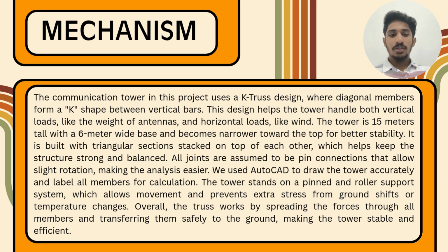The tower is 50 meters tall with a 6 meter wide base and becomes narrower toward the top for better stability. It is built with triangular sections stacked on top of each other, which helps keep the structure strong and balanced. All joints are assumed to be pin connections that allow slight rotation, making the analysis easier. We use AutoCAD to draw the tower accurately and label all members for calculation.